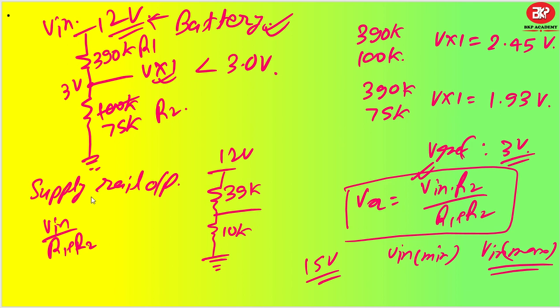Understood? If it is a supply voltage range, let's say you have some LDOs or switching regulators, and that's how you are generating 12 volt, then you can take a little bit lower values of resistor also, so that your current becomes just less than around a milliampere. But at the same time, whichever power source you have, whether it is 12 volt or 3.3 volt or 5 volt or 9 volt or 7 volt, try to keep the resistance division in such a manner that the node voltage comes less than V reference.